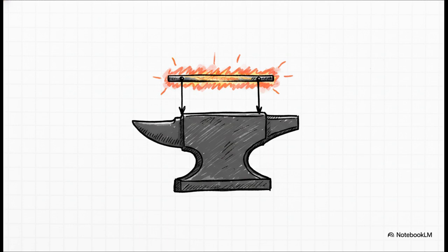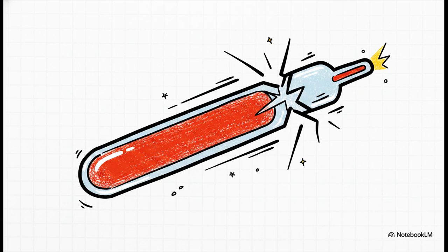Imagine we're building a vessel using a standard stainless steel plate, specifically SA240-304L. If our calculated design temperature is 200 degrees Celsius, we follow the table and find an allowable stress of 110 megapascals. Just to visualize what that actually means in the real world, a tiny 1 centimeter by 1 centimeter square bar of this specific steel could safely suspend about 1 ton of weight, even while baking at 200 degrees. Pretty wild, right? But here's where the math gets really unforgiving.